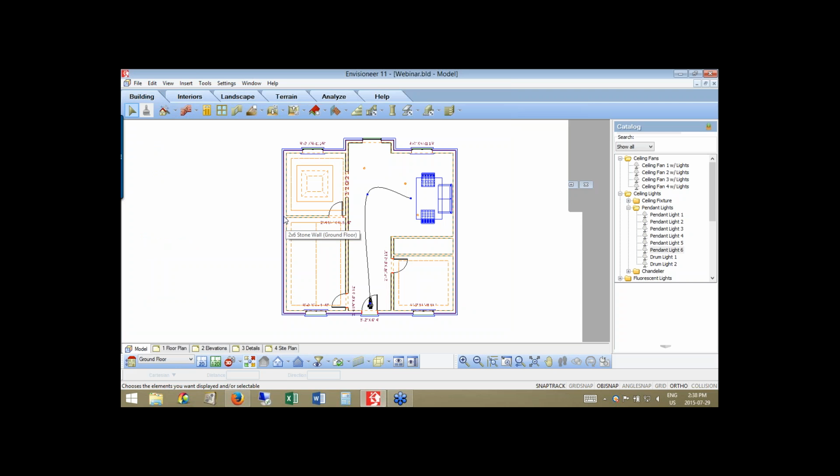We used walls by baseline for exterior. We talked about waiting for the object snap at each corner. We talked about using the enter insertion offset option so that we can start a wall a specific point away from a corner. And we also talked about duplicating walls to create a wall right side by side another one that already exists.